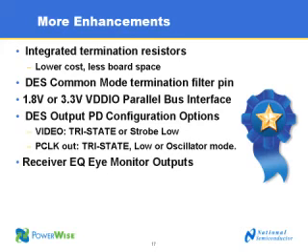Now what we've also done on the deserializer, we've provided a common mode termination filter pin. Let me explain a little bit about that. If you had external resistors, you'd have a common mode point available. Because we've integrated these, we've pulled that point out, and this allows the user to connect the common mode to a capacitor to ground and stabilize the common mode voltage. This is really important in the automotive industry in particular because they do what's known as a bulk current injection test, and this can move the common mode all over the place. And what we want to do is stabilize that so that we guarantee the integrity of the data being received under these harsh testing conditions.